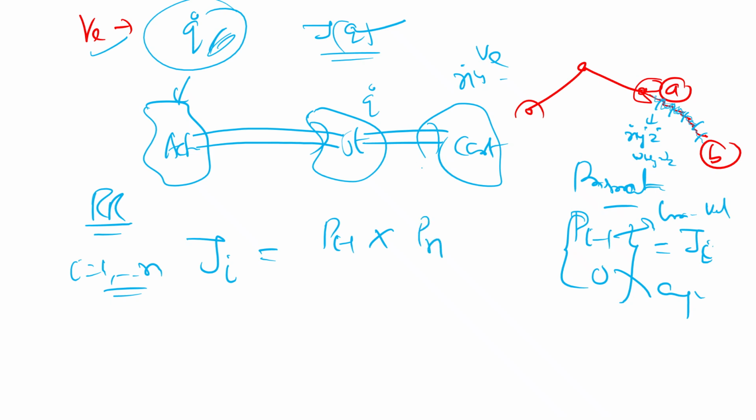So P(n)(i-1), and then here Z(i-1). This gives the linear velocity, and this gives the angular velocity. Definitely in a revolute joint, you will have angular velocity. As the result of angular velocity, you will have some displacement or some movement, so that is linear velocity. This is the Jacobian for the revolute manipulator or revolute joint. This is the Jacobian equation for the prismatic joint.